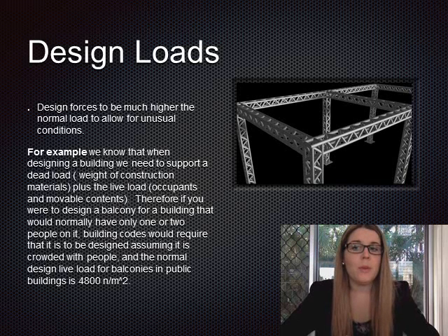So for example, when we're designing a building, we know that we need a dead load and a live load. Therefore, if you're designing a balcony for a building that would normally only hold 1 or 2 people, you'd use building codes in the design, assuming what would happen to the balcony if it was crowded with lots of people.